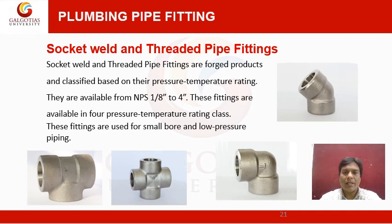Socket weld and threaded pipe fittings. Socket weld and threaded pipe fittings are forged products and classified based on their pressure temperature rating. They are available from NPS 1/8 inch to 4 inch. These fittings are available in 4 pressure temperature rating classes. These fittings are used for small bore and low pressure pipings.